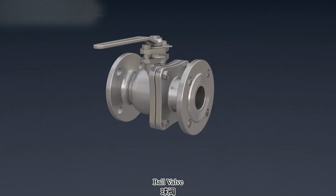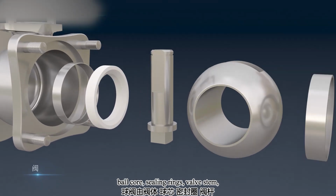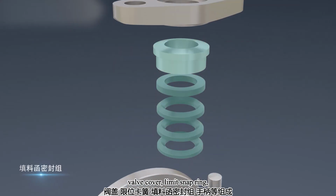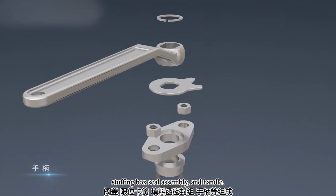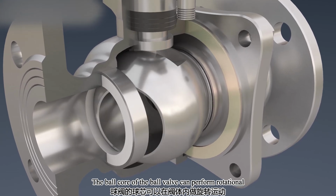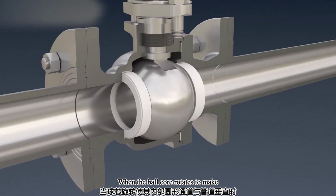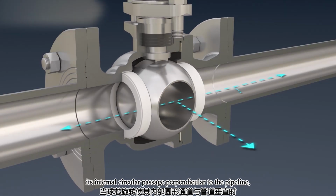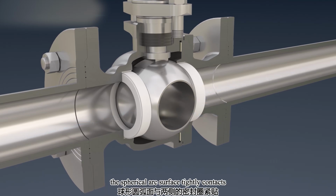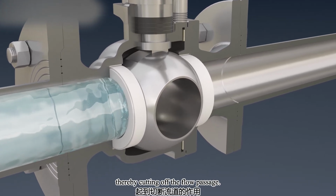Ball valve. The ball valve is composed of the valve body, ball core, sealing rings, valve stem, valve cover, limit snap ring, stuffing box seal assembly, and handle. The ball core of the ball valve can perform rotational movement within the valve body. When the ball core rotates to make its internal circular passage perpendicular to the pipeline, the spherical arc surface tightly contacts the sealing rings on both sides, thereby cutting off the flow passage.